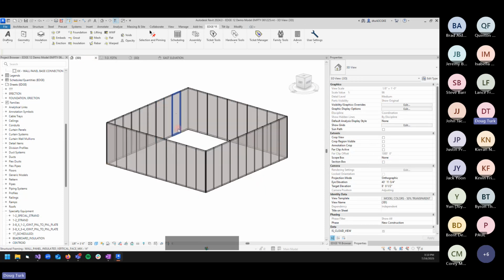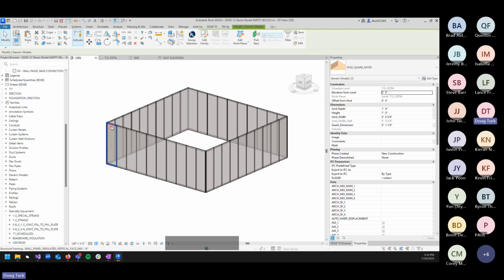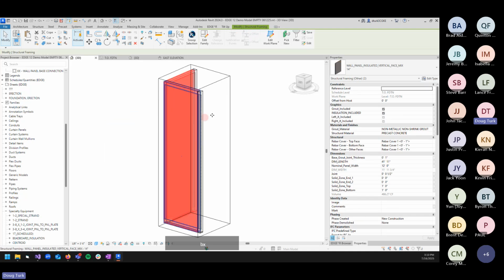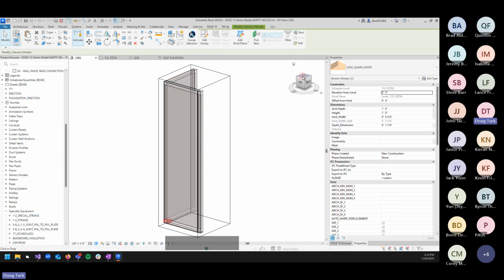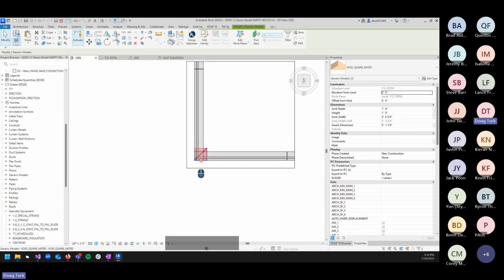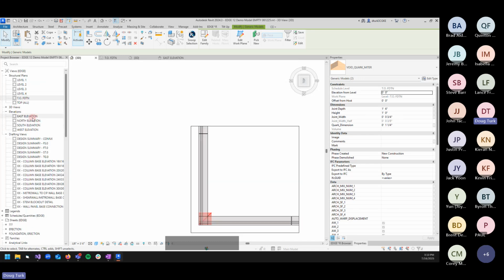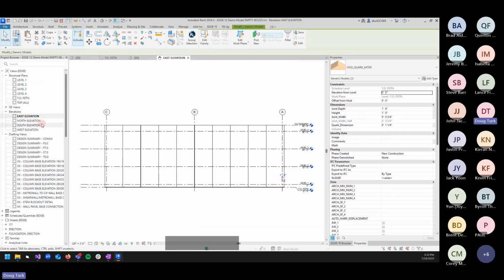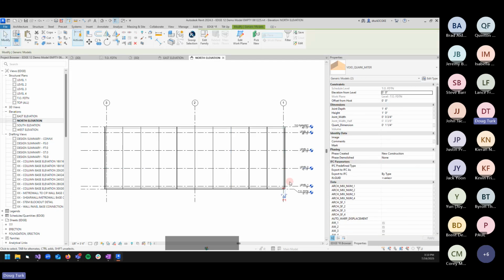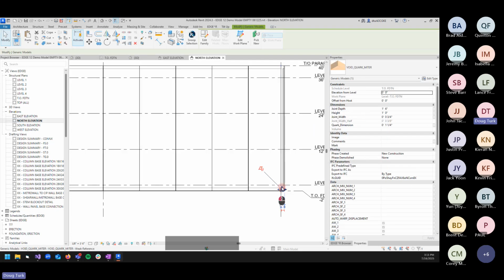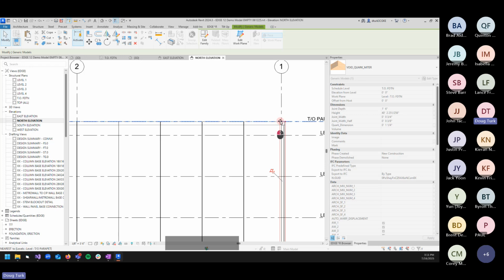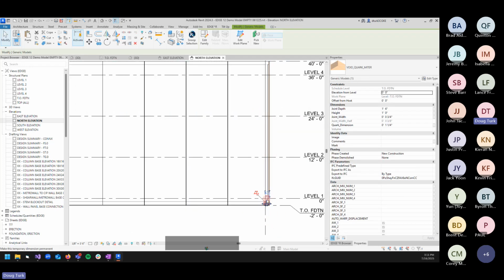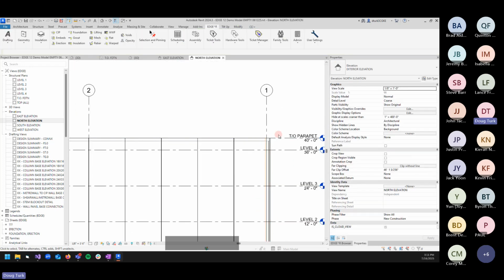So we're going to return to our 3D view, find that, and let's go ahead and section box our corner, which is a Revit out-of-the-box function, which will bring your view to match whatever you're trying to look at there. And we can see very easily what we're working with. Now, before we get into all of that, let's hop over to the north elevation. And we can again use those shape handles to pull this up to match the height that we want. Go ahead and do that. And now we should be good to go.